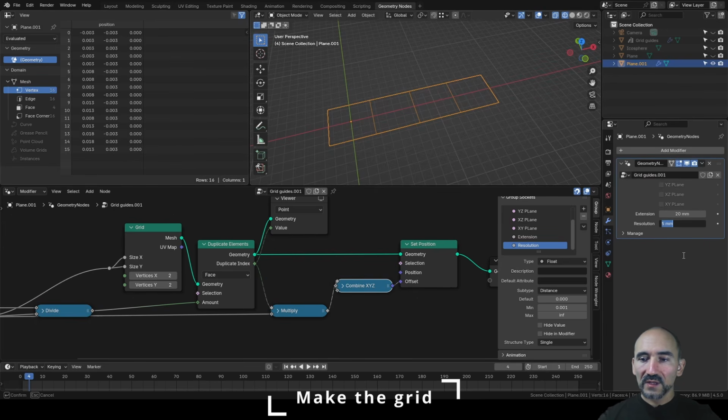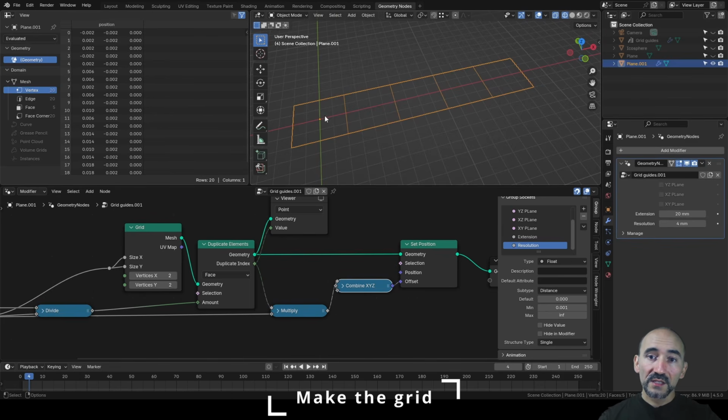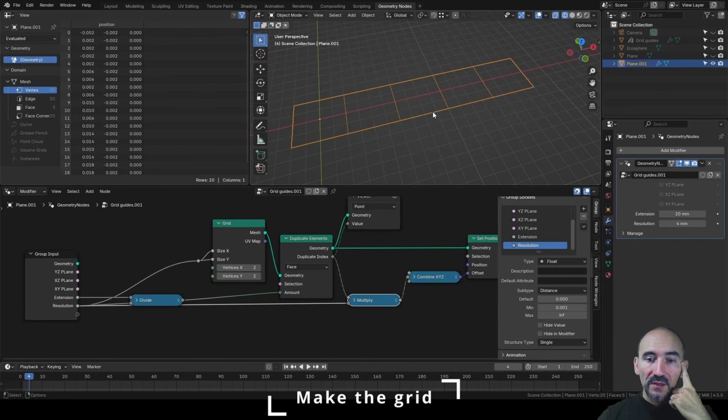And if I, for example, set a resolution of 4, we have 5 squares in this row, but the center of the entire row is in the middle of a square, and we don't want this. We need to have an origin point at the center, and from this point start to have the correct plane and squares around this origin point. And with an odd number of squares we cannot get this result. We need to calculate the correct number of squares based on the division between the extension and the resolution.